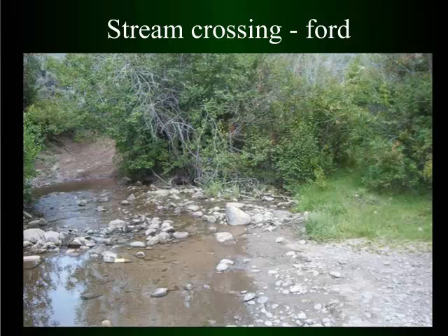It's nice if you can take some of the grade out so it's not too steep, and then put some good clean open rock on both sides. A rolling dip, water bar, something to intercept water off the road surface itself and kick it off so it can filter before it actually reaches the stream. And then using open rock with no fines in it, with no dirt, to go across the stream here so you don't add any sediment when you dump that in there.